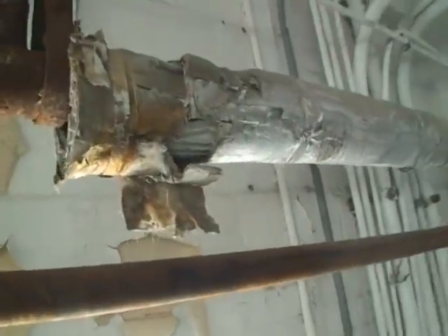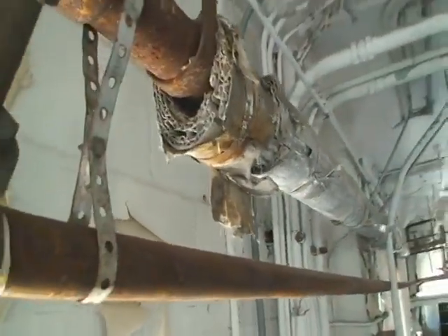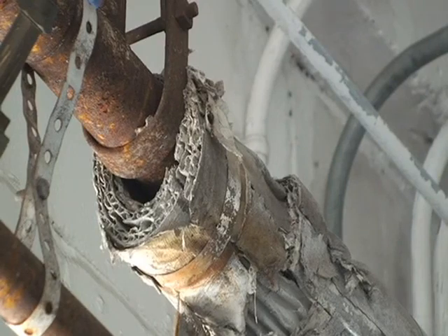This is a really friable material. It's a regulated asbestos containing material. Air cell will always come back positive. Earlier we looked at some preformed pieces of pipe insulation. Sometimes those come back positive, sometimes they're negative. Air cell will always test positive.